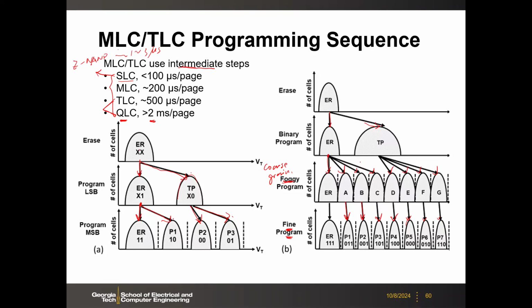If you read the tech news of this industry, at the very beginning of the semester I talked about storage class memory, right? People try to bridge the gap between the DRAM and the NAND flash. Companies like Micron and Intel announced a product based on 3D XPoint, which we are going to discuss later in the phase change memory section. That product failed.